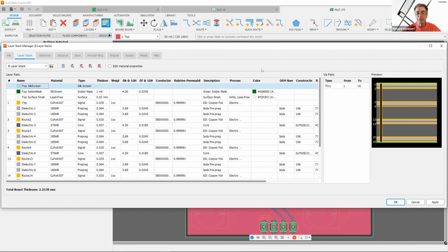We also had in Eagle, for example, there we were very flexible in building the boards. Drills from here to there, micro vias from here to there, and then layer setups, crazy layer setups. You can still do it, but of course, the standard setups, an 8-layer stack up looks like this. You decide maybe on copper thickness because you have high current, you have thicker copper foils. Of course, that's easy to change, and all this information goes also into the ODB++ export, for example.